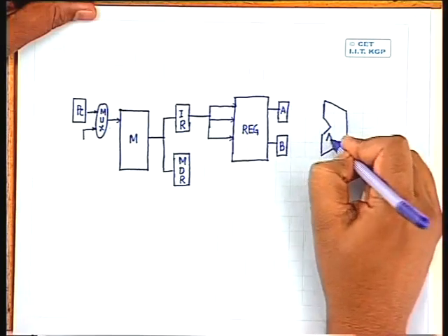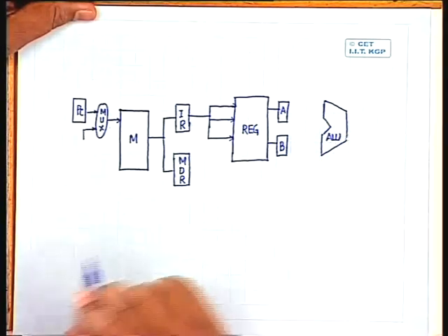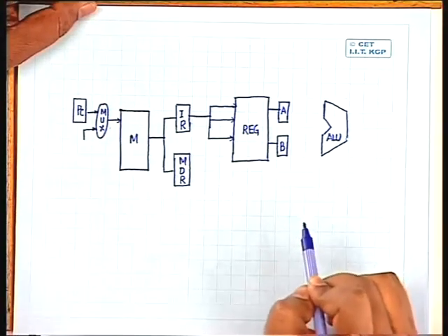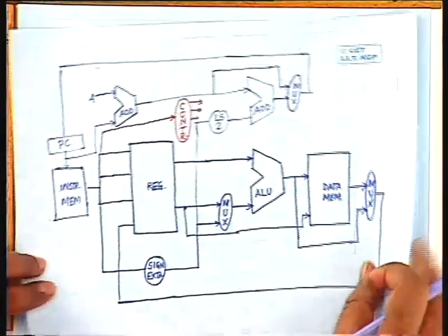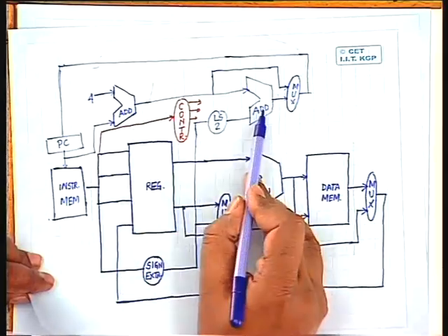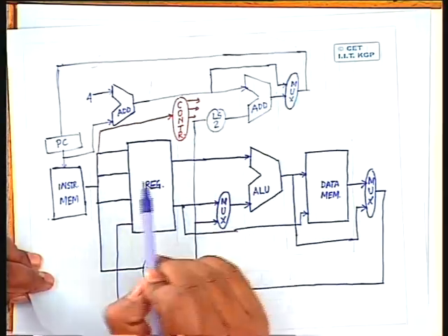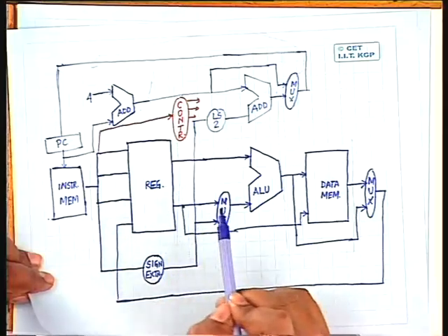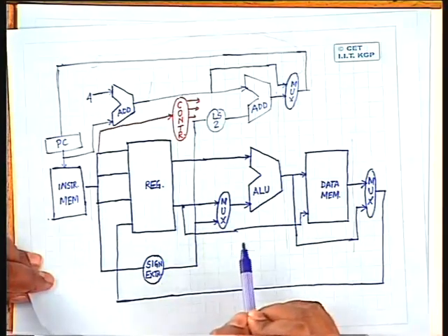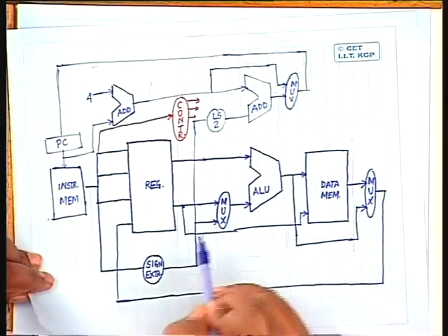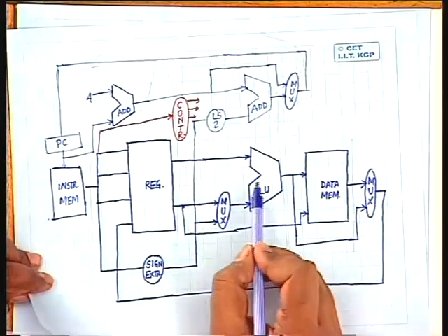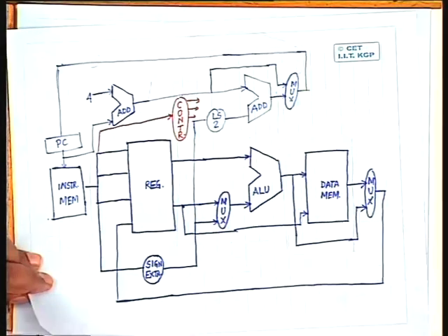So this is the ALU. Now our aim is that in our basic design we had two adders and one ALU. These two adders are responsible for computing the instruction addresses, and the ALU was used for executing the register type instructions and also for calculating the memory data address. Now all these we want to perform with the help of a single ALU.